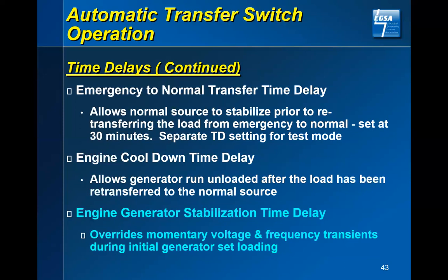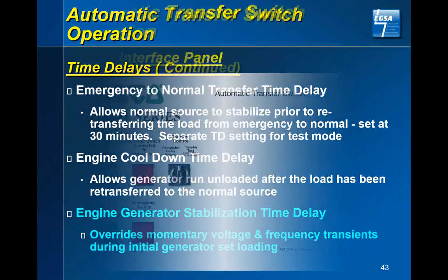And then the next one is the generator stabilizing time delays. We've talked about that. When you're doing that, your generator may be able to run all loads connected, but starting everything at one time may be a hardship on it, and specifically your larger equipment loads or those type of loads that can be delayed for a while.